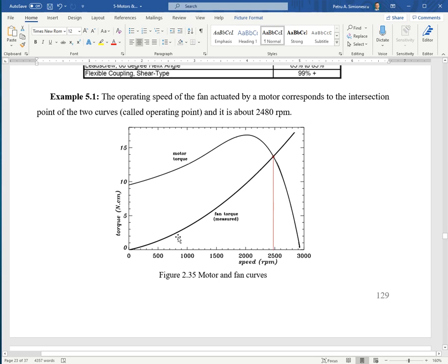All right. Now, if I have a too large fan, a too small motor, this curve would be somewhere low, and you'd have an intersection. So imagine this being steeper, or this being reduced in scale, and this staying the same. That is a smaller size motor. If I have the operating point left of the maximum torque, then this would be an unstable operating point, because a slight increase in load could induce stalling.